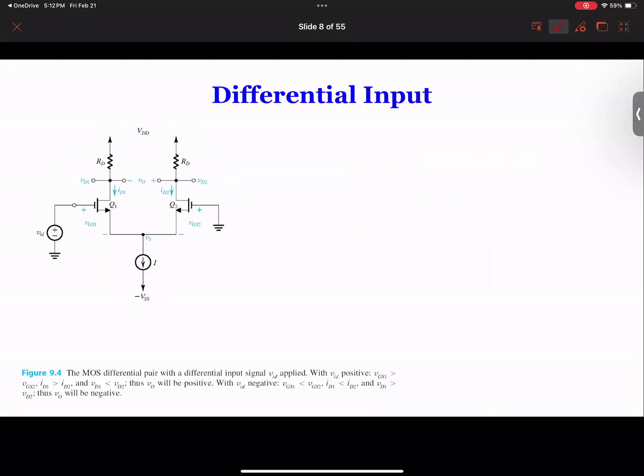And next week, we're going to talk about the impact when you have a common mode, because I said many times that the transistors are 100% matched. But in the process of making these devices, you cannot have them 100% matched. Then what happens? There's going to be some difference between these two outputs. So you're going to start to see, even though you have the same input, because of the mismatch of these two transistors, you're going to have output at the two terminals, right?